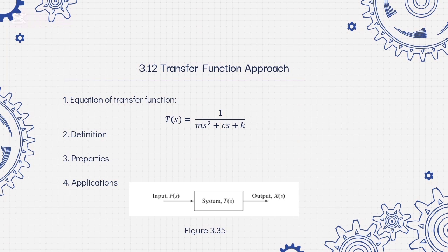And also, as we see in figure 3.35, the transfer function can be represented as a block diagram where the input and output are shown on the left and right side, respectively, of the block, with the transfer function shown inside the block. And note that the denominator of the transfer function is identical to the characteristic polynomial of the differential equation. And now we'll talk about the solution using Laplace transforms.